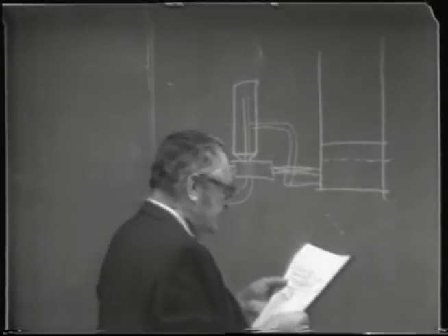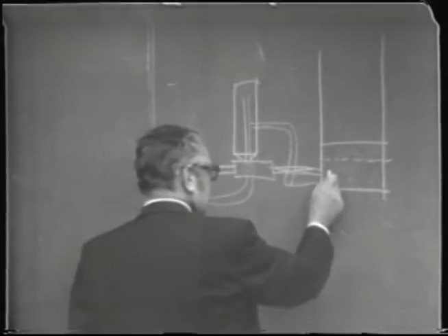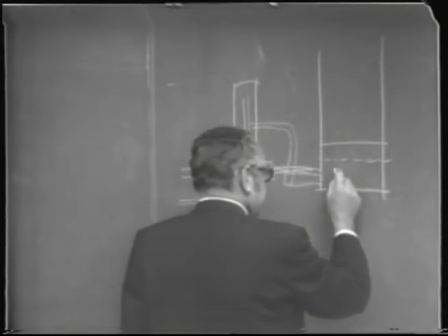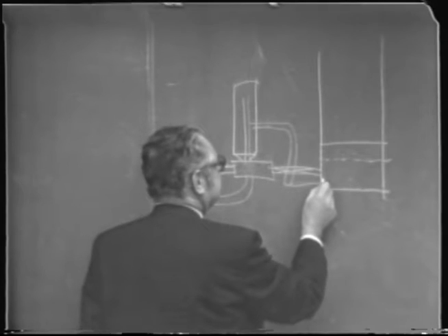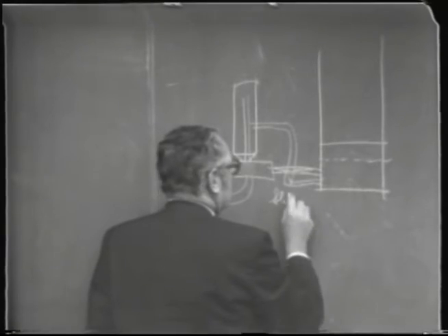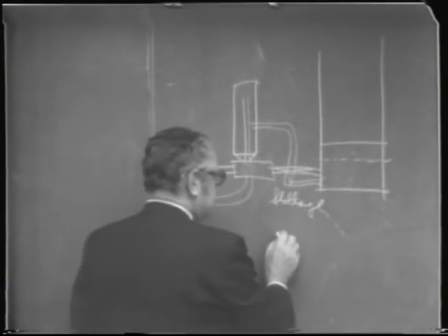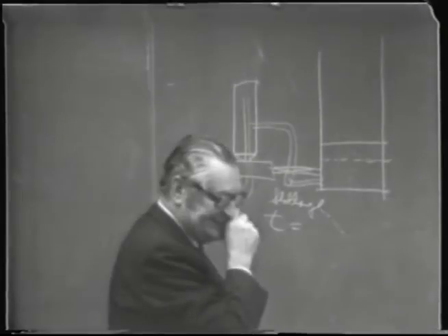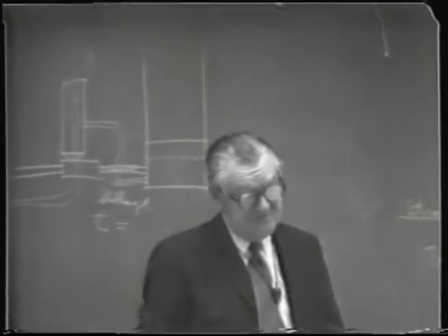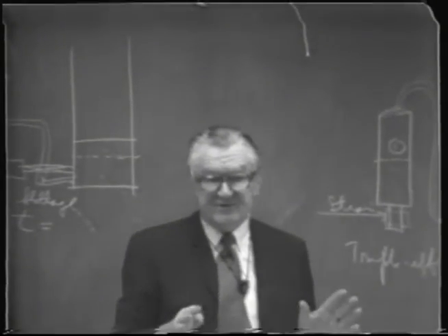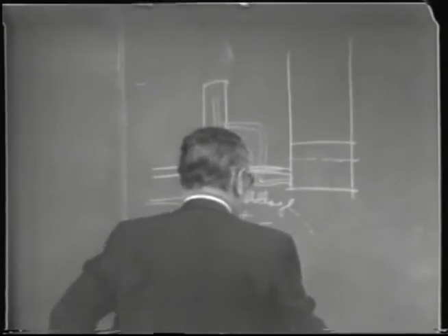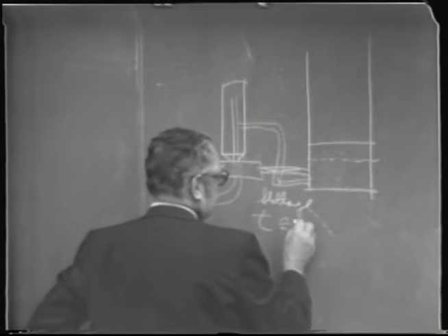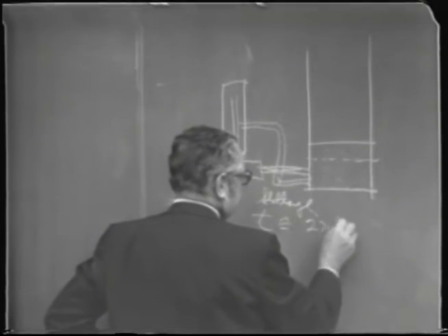Anyway, this stillage here has a temperature as it leaves the still of somewhere around 212 or higher. It'll always be a little bit higher depending on the base pressure. So the temperature might be, for example, 220 degrees Fahrenheit.